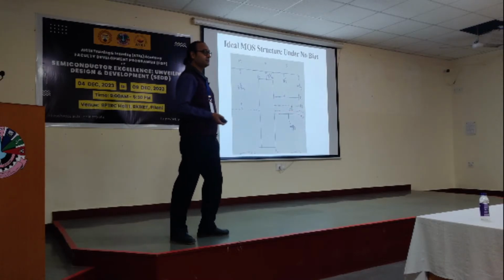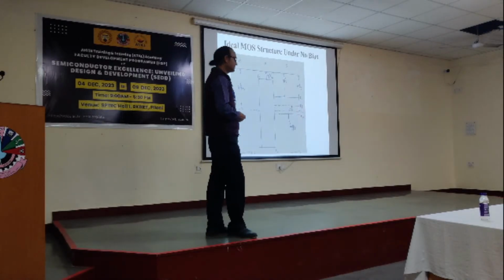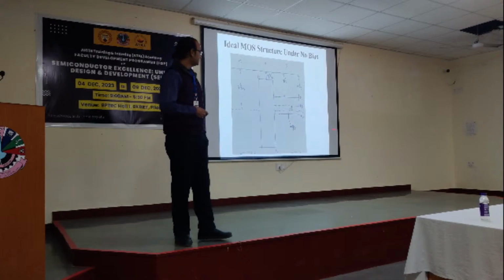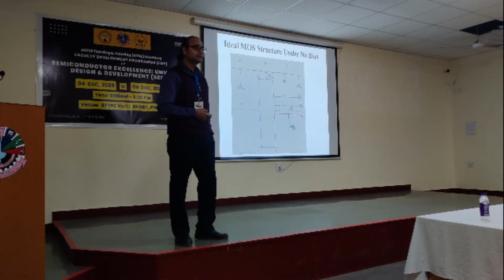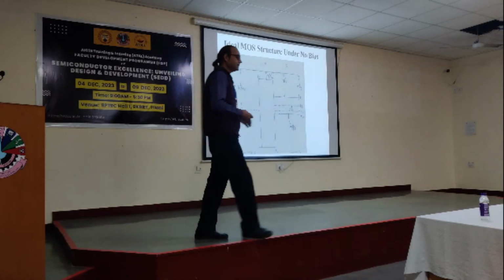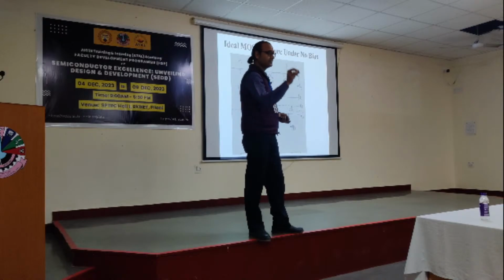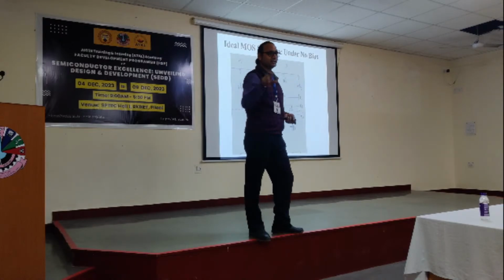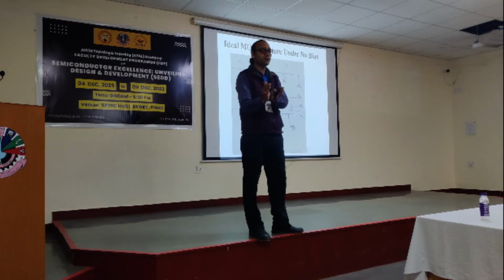Fermi level, where does this come from? Why is this Fermi level shifted? Because of doping. Due to doping, what happened? We have introduced acceptor ions, acceptor atoms. Now what will an acceptor atom do in the semiconductor? An acceptor atom will accept one electron and the result will be one acceptor ion plus one hole.